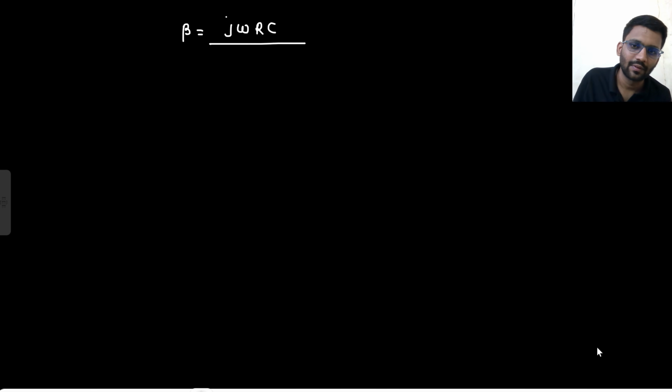So what is my feedback factor beta? I will put S equals to J omega. So J omega RC upon 1 plus 3J omega RC minus omega square R square C square. Say yes or no. Right?